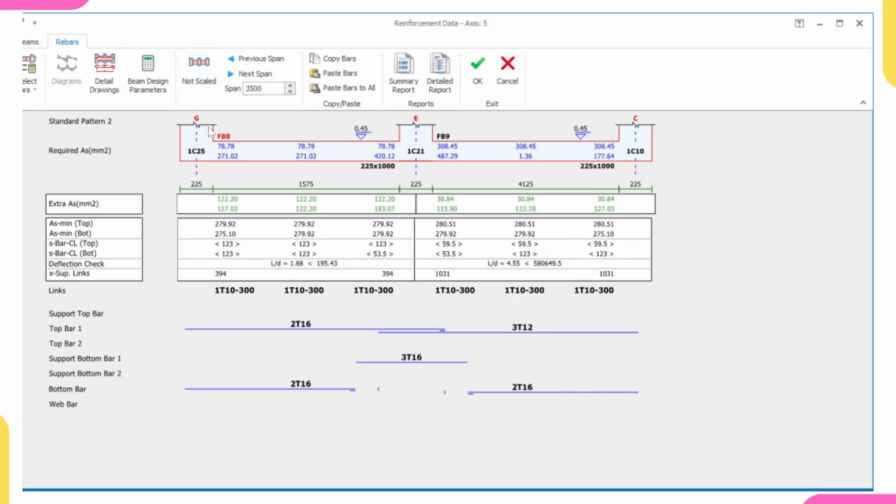If it's a normal beam, our moment diagram will be like this. It will go like this, then come down like this, and then like this. That means we will be reinforcing the top because of the hogging moment. But in this beam raft foundation, the moment is going in this direction, going up, then here it will come down, then go up, then terminate at 0. So that hogging moment is now at the bottom. We will be explaining the governing principle behind all this, so you understand this. Just stay tuned till the end of this video.